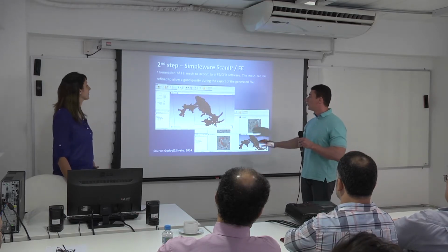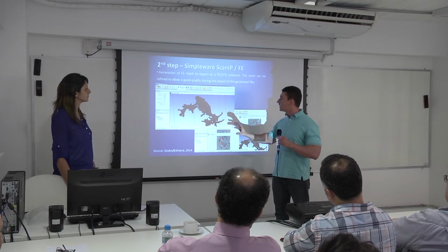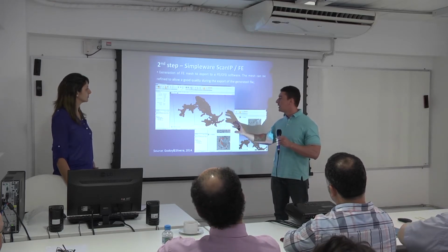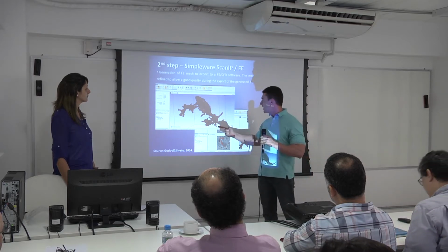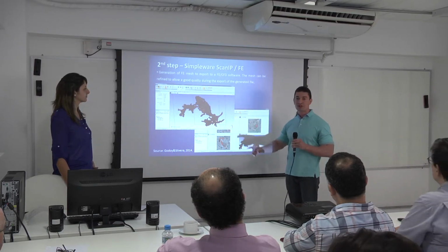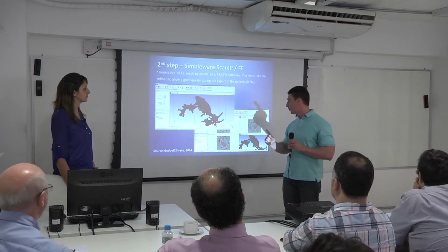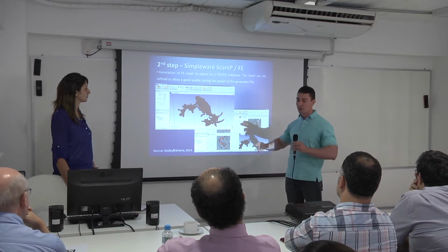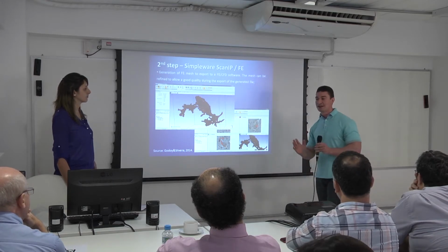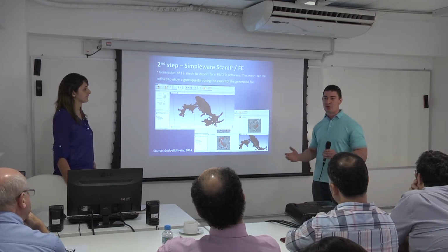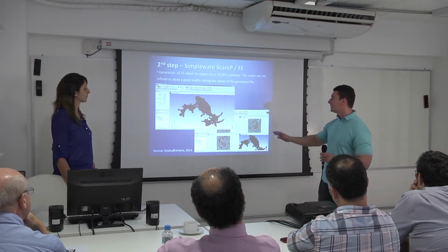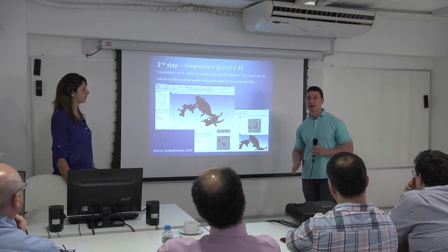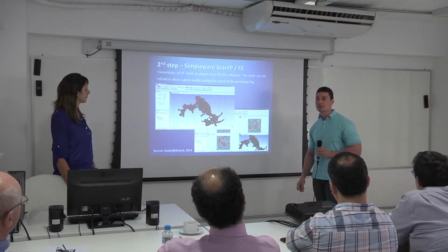And then we can separate the interconnected pores and generate the mesh through the FE tool. This mesh here represents the interconnected pores of that real rock. In this case, we are trying to work with a mesh not so big, because we do not have software that is too powerful. But we think that the size we have created here, something around 300,000 mesh elements, is quite good for us.